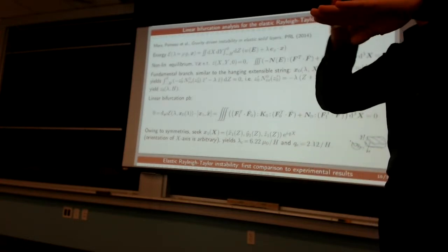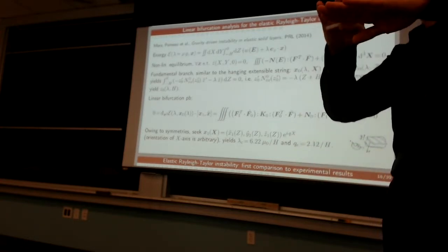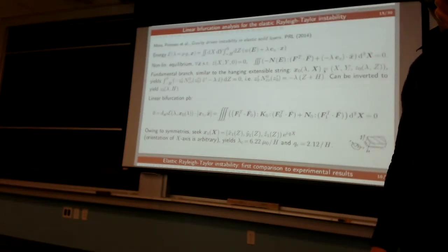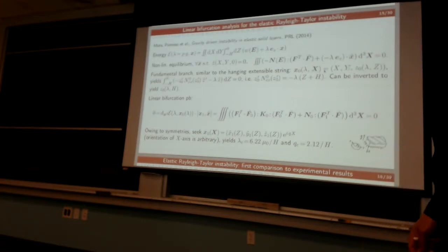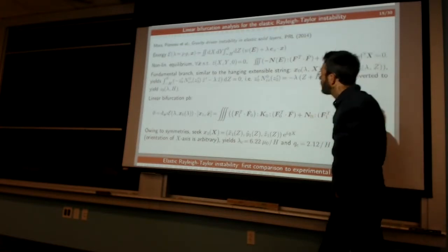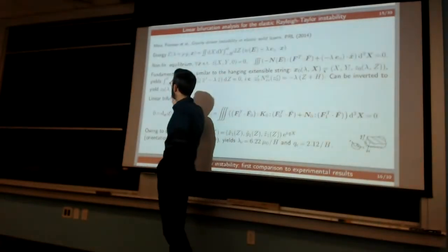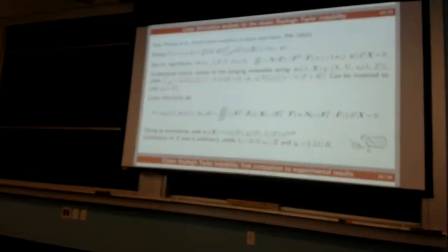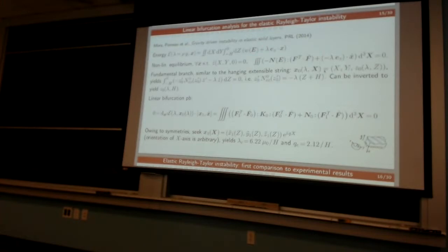You can guess what the internal stress is going to be. And if you invert the constitutive law, you find the stretch from this internal stress. So that's exactly what guides the solution. And you end up with an explicit formula for this theta. So that's going to be my reference configuration. And again, my fundamental solution, as you see, is making some assumptions, assuming that the symmetry is preserved here.